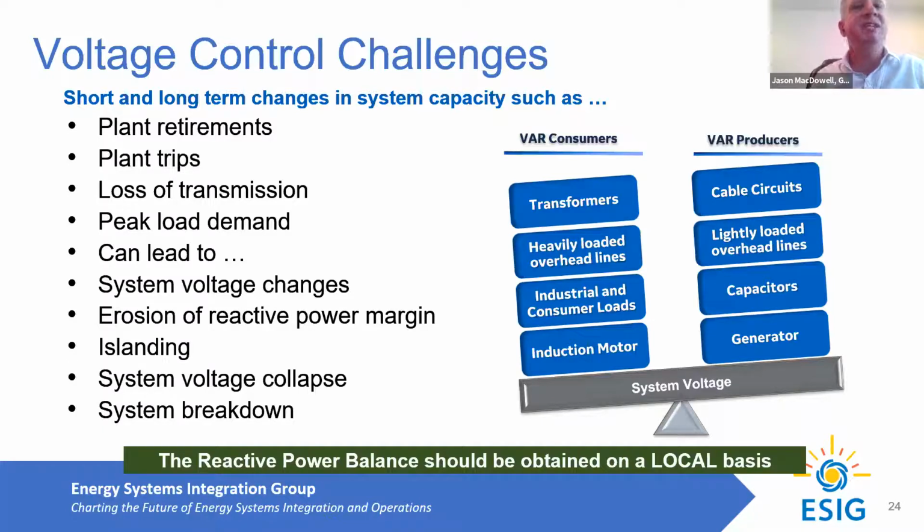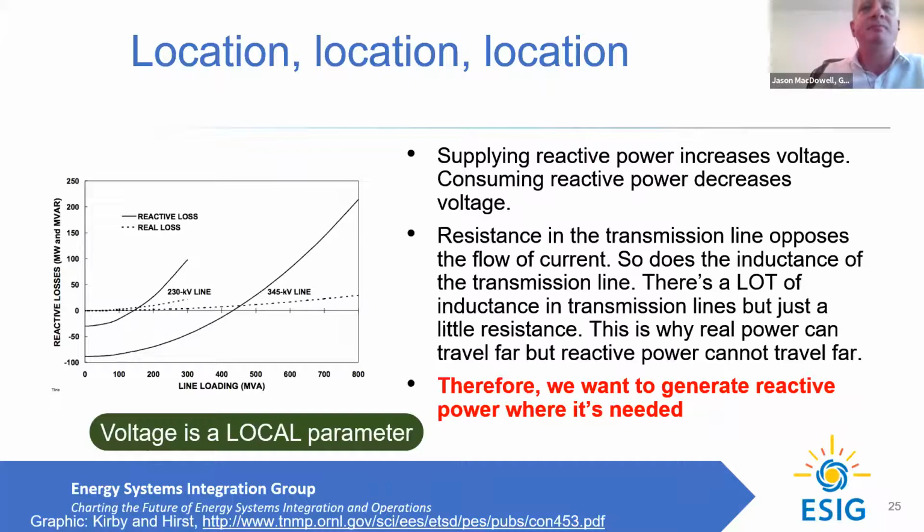And if any of those things happen, you can slip away and the voltage can ultimately collapse, or you can trip parts of the grid offline. So maintaining that voltage balanced, stably and reliably, is a very key aspect. And again, location, location, location. Making sure that we look at all the integration of individual resources, individual plants, at that particular operating point is very critical.